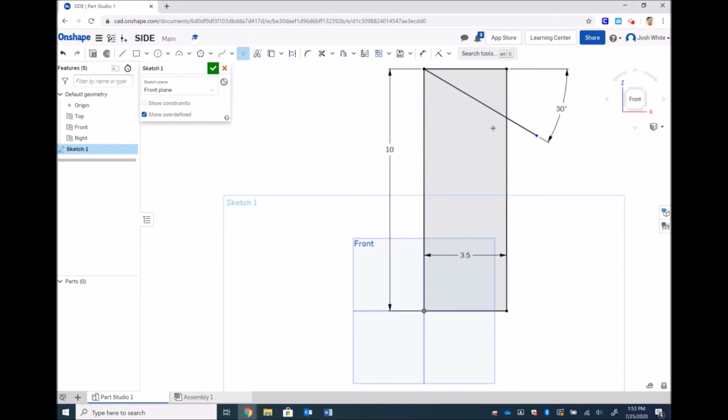So from there to there, it's approximately 8 inches, which is what I did on the drawing, and that's not necessary to do that dimension. That's an over-constrained drawing. So we'll just undo that. So we have our angle set. Now we could trim off everything and make it just the profile that we want, but we don't have to, and I'll show you why.